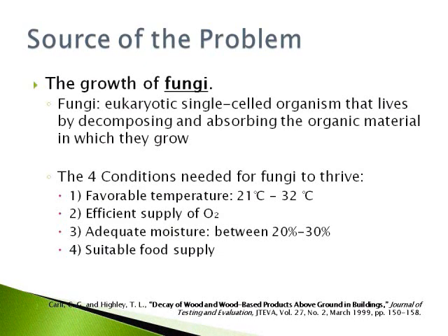The third, for most decay fungi, requires adequate moisture. To achieve this condition, the best moisture content of wood for fungus is usually between 20 and 30%. The last condition is that wood decay fungi must receive suitable nourishment, which it gets by digesting wood cell walls, thus causing the deterioration of the wood.